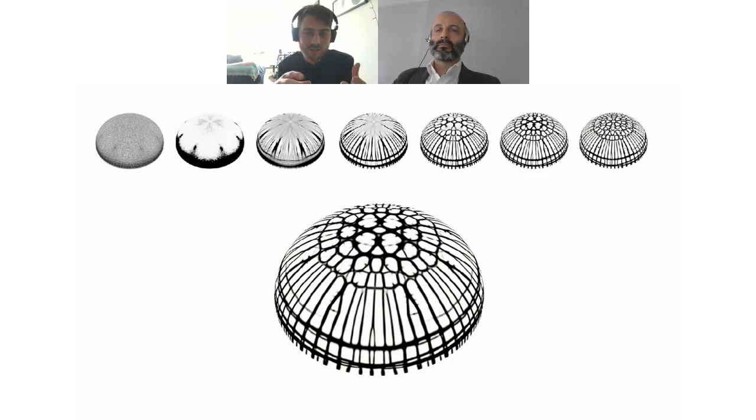And in this case, it's interesting to look at, well, what is the solution here, and can we learn something from this? So you can see that at the top, you've got a grillage arrangement because it's quite flat. Then as you move down, you see that you're getting columns forming. And then at the bottom, because it's bulging inwards, you've got these tie beams. So it helps to understand what's happening, as well as provide some ideas.